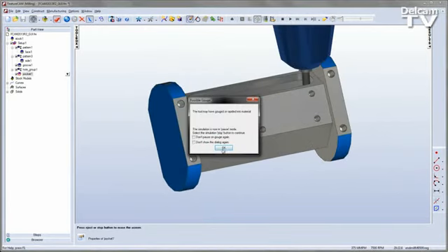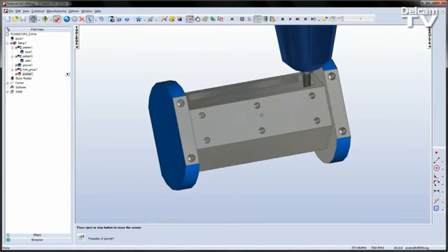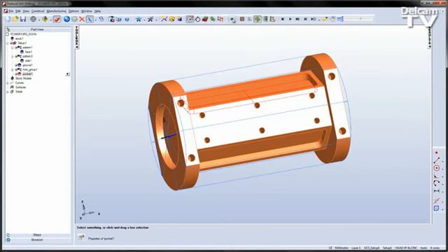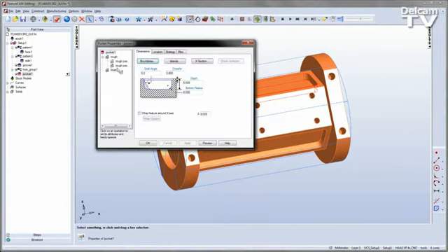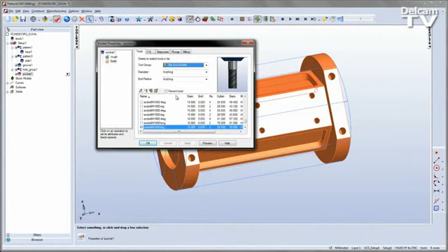In this case you can see I've gone through my simulation and indicated a gouge, so what I want to do is make my tool longer. Go into the pocket and modify some parameters. So I'm going to select just a single tool to do my roughing, and then for my finishing tool I'm going to select a smaller tool, something that will be able to machine this particular pocket.